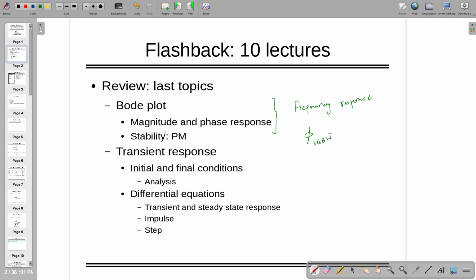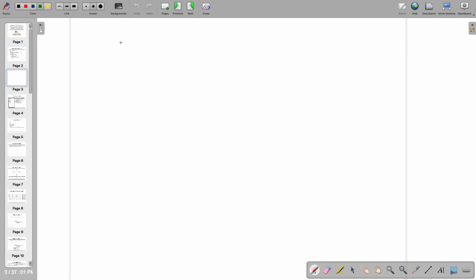But before this, there is one more measure to find out whether the system is stable or not. You need to check all the roots, meaning poles and zeros, both have to be on the left hand side of the S plane, right?